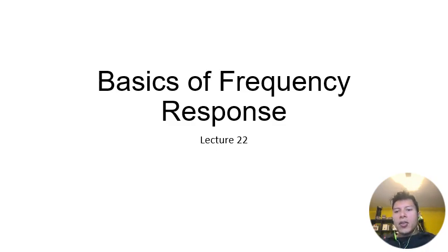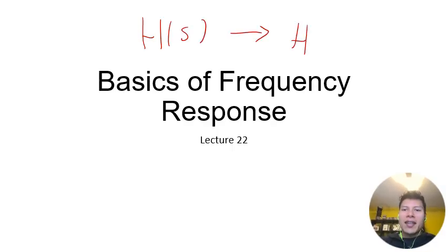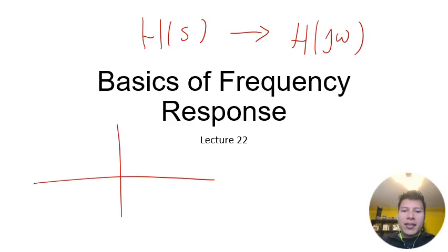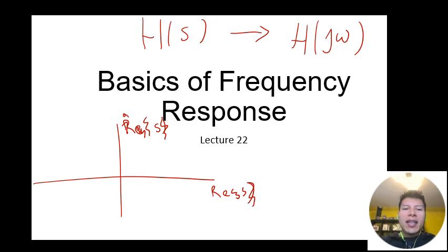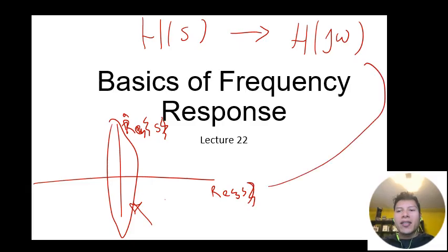Okay, today we will go over what we call the frequency response, and in particular, the frequency response is your transfer function, H of s, when you evaluate it along the imaginary axis. So you can evaluate your Laplace transfer function anywhere on the complex plane. Whenever we evaluate it on the imaginary axis, we're going to call that the frequency response.